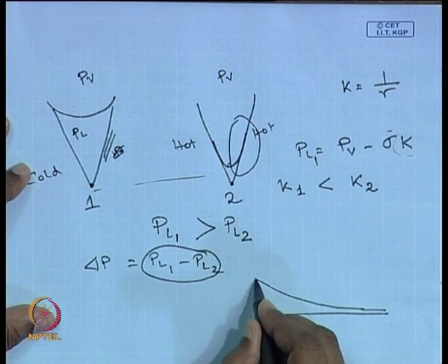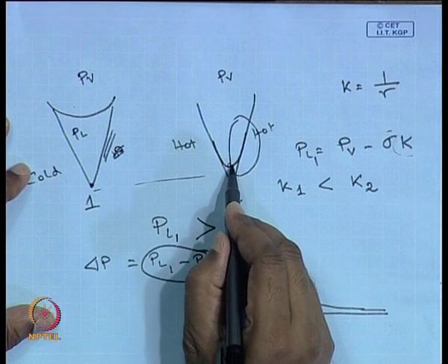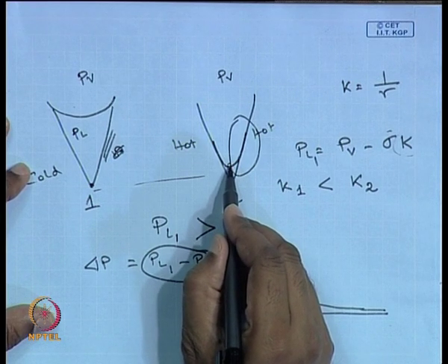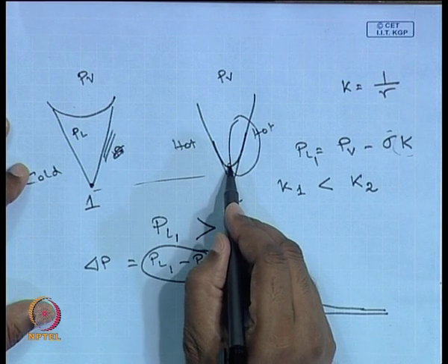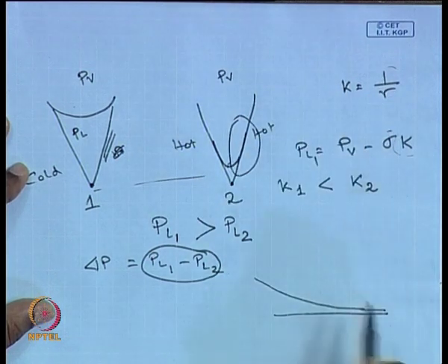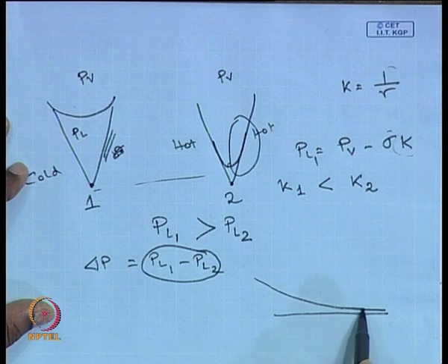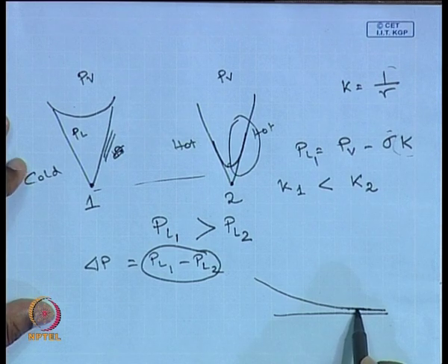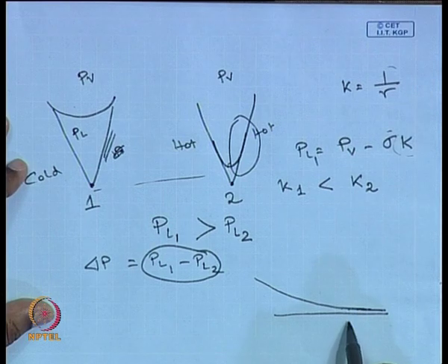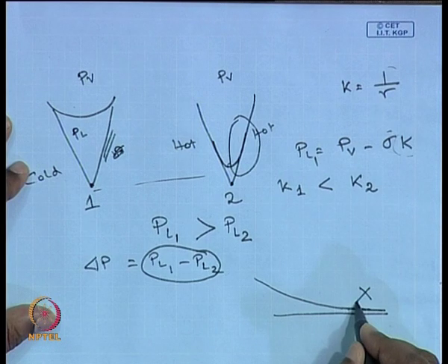Okay. So, this goes towards the capillary meniscus part or the region where the curvature is constant. This is called the macro part of the meniscus, where the curvature is given by simply 1 by r, r being the radius of curvature. But as we move along the wall, we will come to a point where the liquid forms a very thin film on the solid surface, and the molecules of the liquid are attracted so strongly by the solid due to the van der Waals attractive forces that no evaporation is possible from here.